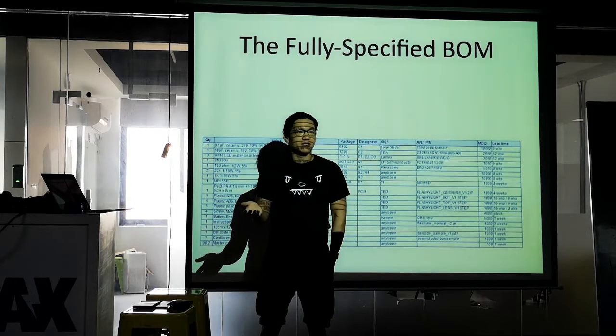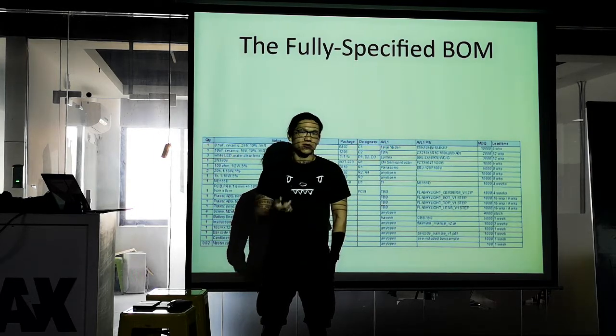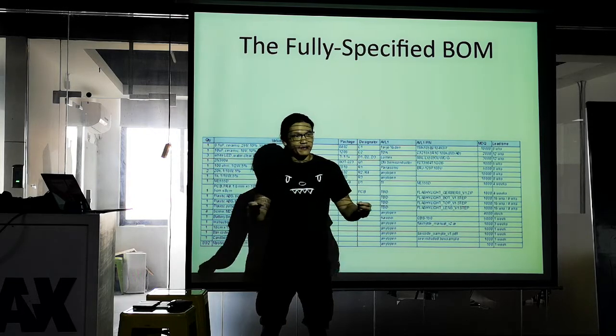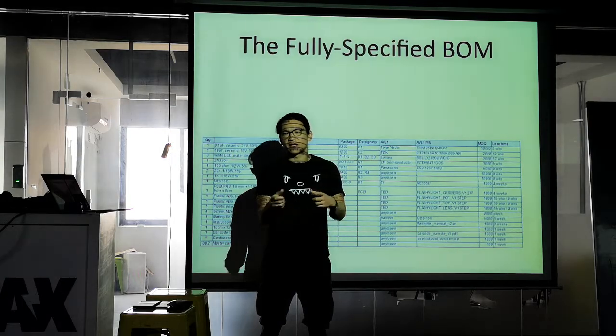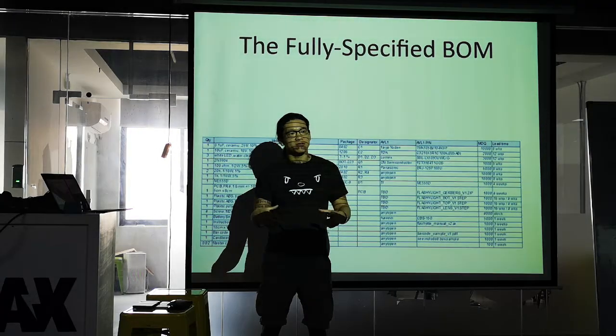I think you're probably just going to have to work with the factory, tell them what we're doing. New product introduction, NPI, a short run. If possible, get cut tape and then put it on the reel inside the factory or something. There's a bunch of things you can do to try to get around these MOQ limitations.